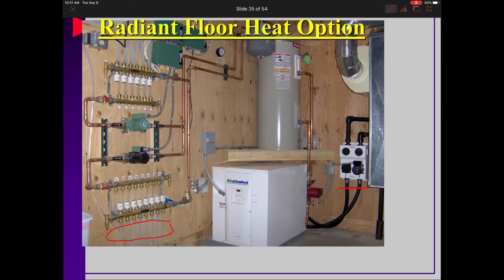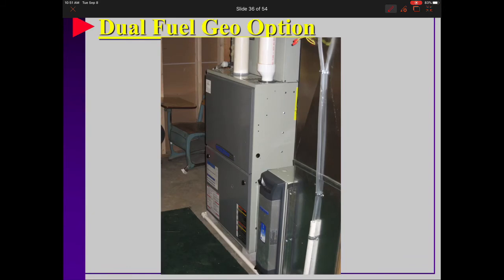So this unit is running all of the hot water right into this little tank, and then we are sending that energy right back into the in-floor heating in this application. So again, very typical application for doing in-floor heating. A water-to-water unit will work quite well for that.